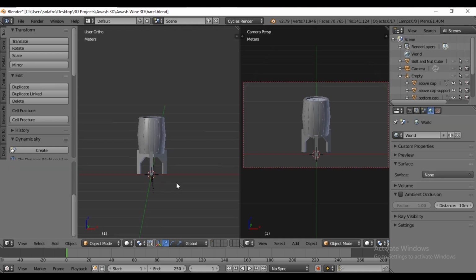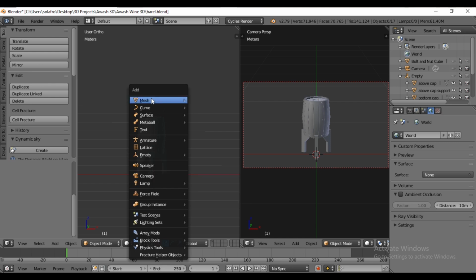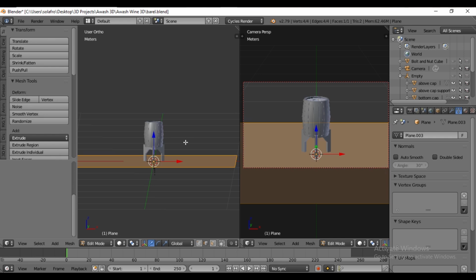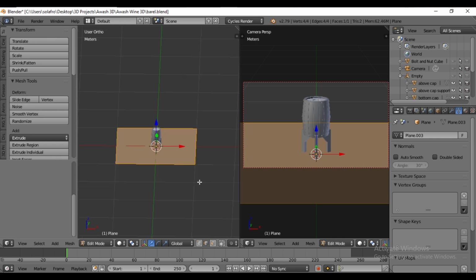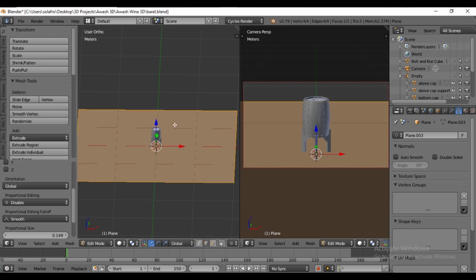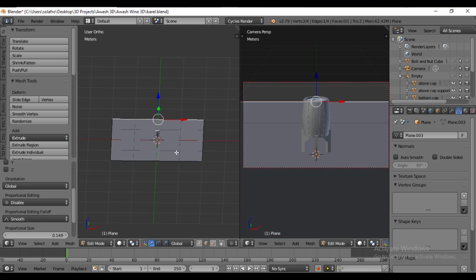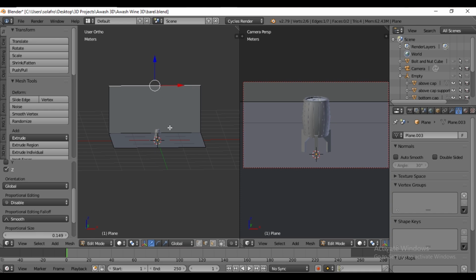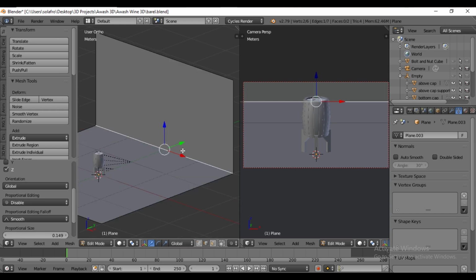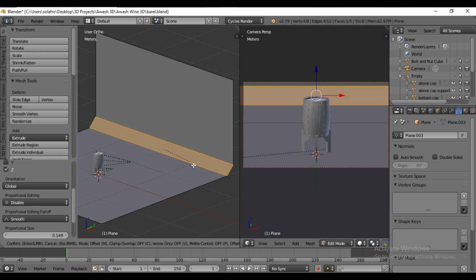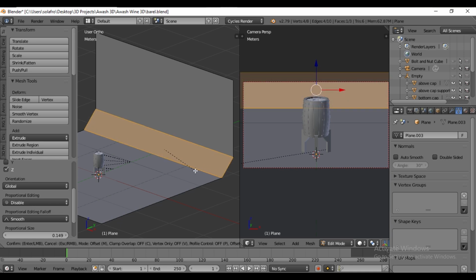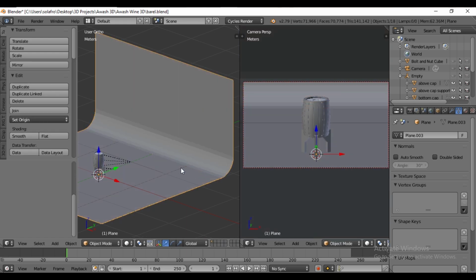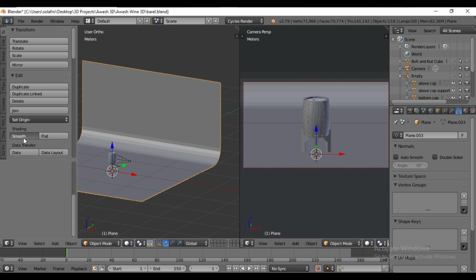Let's create the background by pressing Shift A, selecting Mesh, and adding a plane. Switch to Edit mode and scale it twice by pressing S. Select an edge. Press E to extrude along the Z-axis. Then select the middle edge and press Ctrl B to bevel, adding loops as desired with the middle mouse scroll. Switch back to object mode and apply smooth shading.